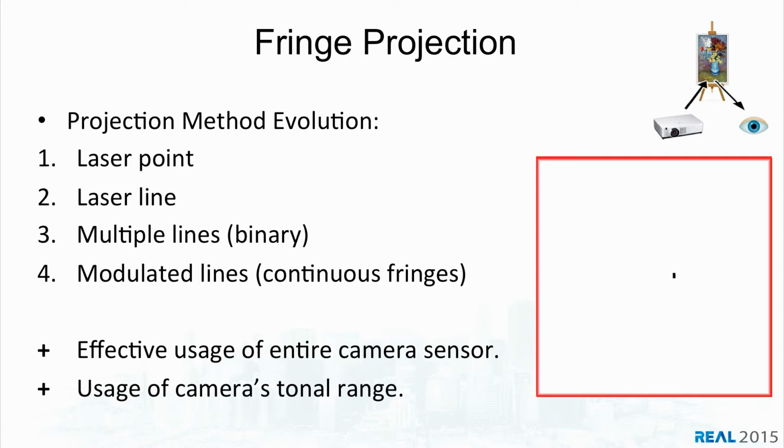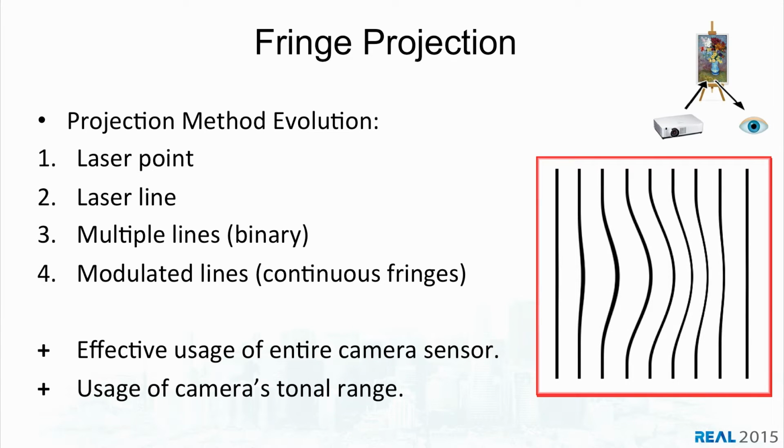Now if you're smart and you have this two-dimensional sensor, you make a line out of it. So you project a laser line, and then you can already see that there's some kind of a structure going on there. And then you can calculate this and triangulate the entire line. If you're even smarter and you think you want to speed things up, you can use multiple lines, as I did here, projecting multiple laser lines and triangulating all of those.